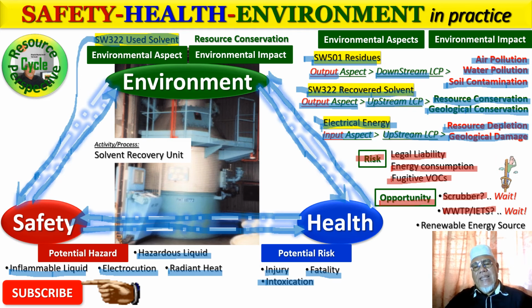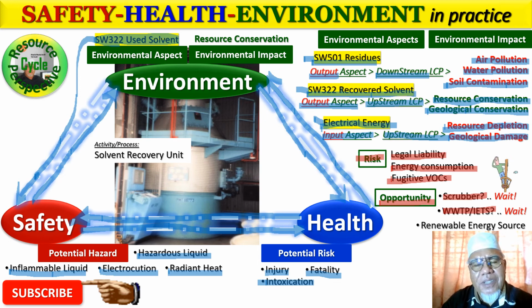Okay, so I believe that might not be the case, and I would suggest, off the record, if there is any emission, there are emissions actually from the local exhaust or from the exhaust of this particular recovery unit. And also we can install hoods around the area to minimize the concentration of fugitive volatile organic carbon in the area itself. We can use adsorbent material. I've done it. We extract those exhausts through a column of adsorbent.